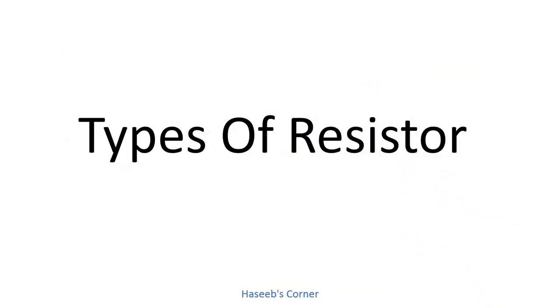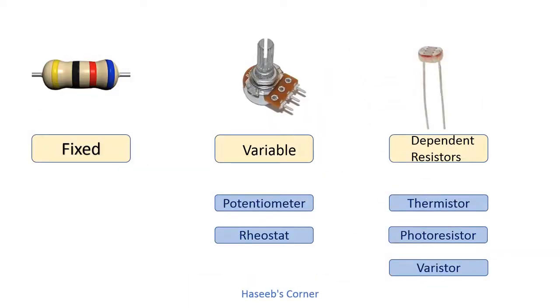There are a lot of different resistor types. All the types have their own characteristics, applications, and construction. Fixed resistors have a fixed resistance value with a particular tolerance value. The general term resistor is most commonly referred to as fixed resistors. Fixed resistors are available in both axial and SMD packages.